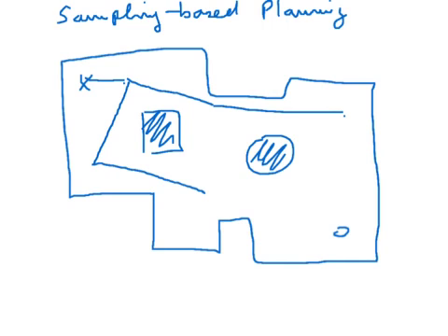How do we know that we actually reached the goal? In practice, you have to define a goal region for which you are happy when you enter it. So let's say we define the goal region as a so-called D ball. In this case, D is 2, so it's a two-dimensional ball or a circle, and we stop the search once we enter this region. So let's say we take another point like this, and finally sample a point in the goal region and find a path.